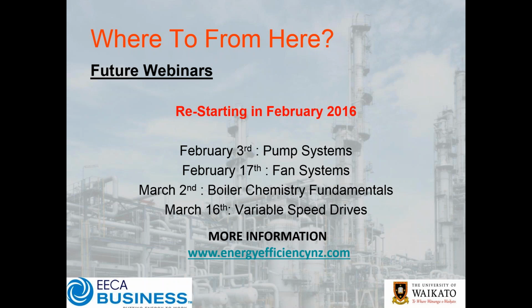And I'm just wondering if you've seen any cases for retrofitting standard pulse jet blow tubes and adding Venturi nozzles, because they're quite pricey per nozzle, and you've got lots of nozzles. And I've seen cases, because obviously if your bag DPs are lower, then the total system energy for your ID fans reduces. So just wondering if you've seen anything or any articles on that.